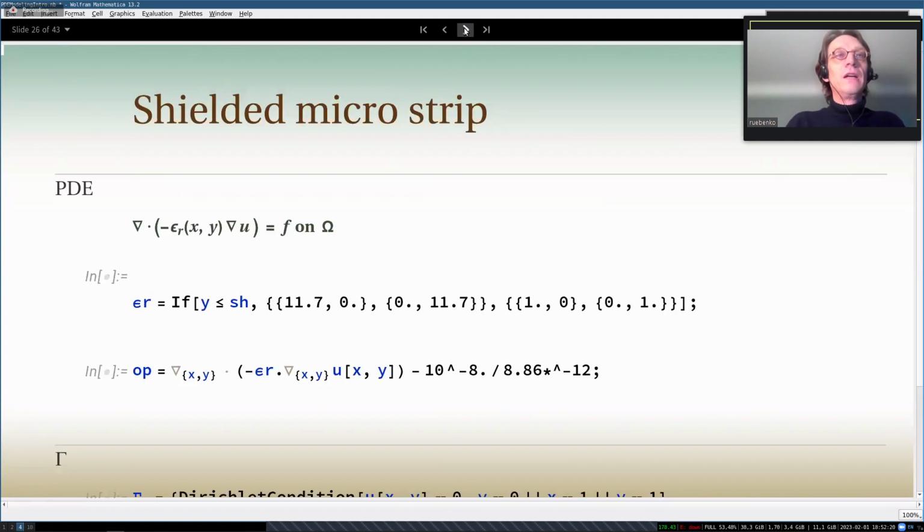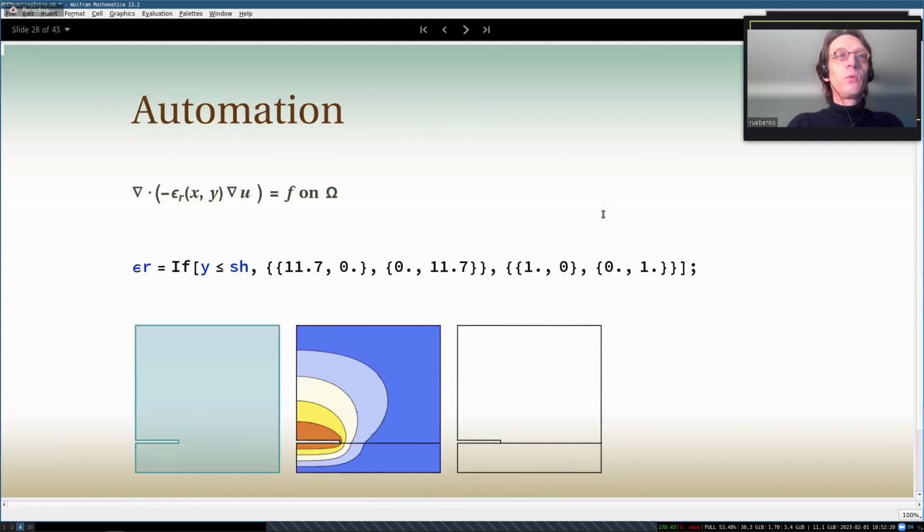But in this case, NDSolve was able to figure out that there is a material discontinuity between these two regions. Just because it could analyze this if statement, it automatically introduced this additional line. And then this is actually the boundary mesh that the geometry is generated from. The reason is that the finite element method works better if the evaluation of this function happens only within the element, if the element doesn't transition material boundaries. So that's something that happened automatically.